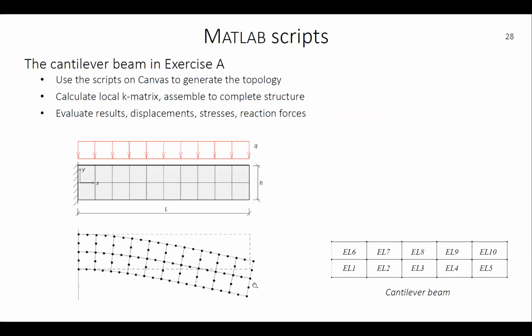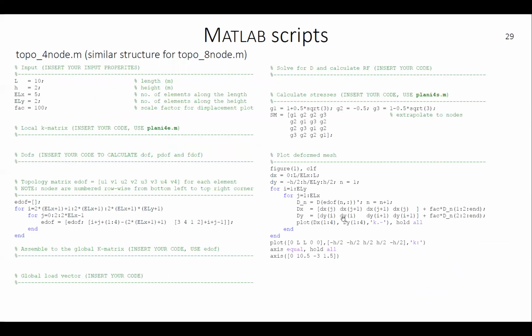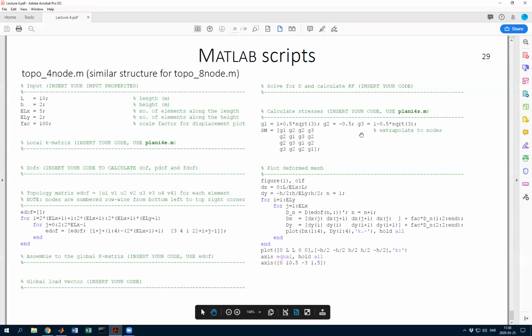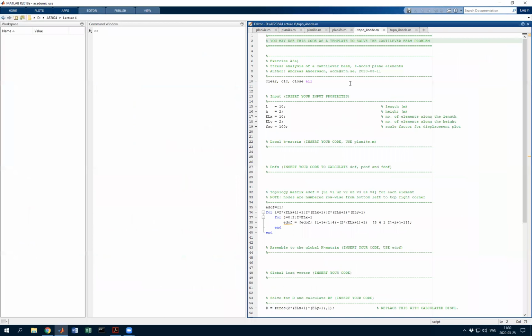And it's also good to make this plot to make sure that the displacement field is continuous, so nothing looks too strange, because otherwise you have likely assembled the system in a wrong way. So that's actually all of the presentation for today. Let's see if this makes any sense of using MATLAB here.